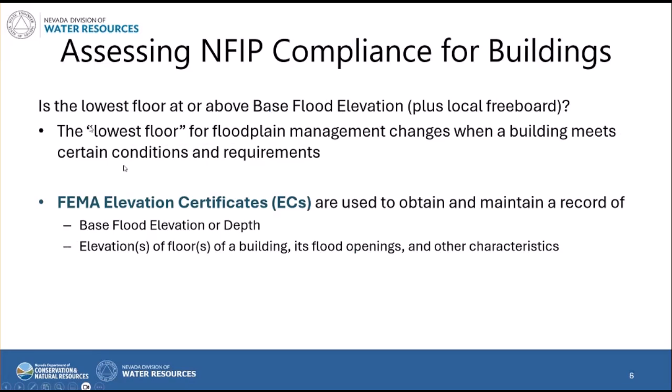So that lowest floor, per that definition, changes when a building meets certain conditions and requirements. Your job as a local official is to make sure the lowest floor is at or above BFE. You have to collect certified elevation information. You don't have to use the elevation certificate form unless you're in CRS.